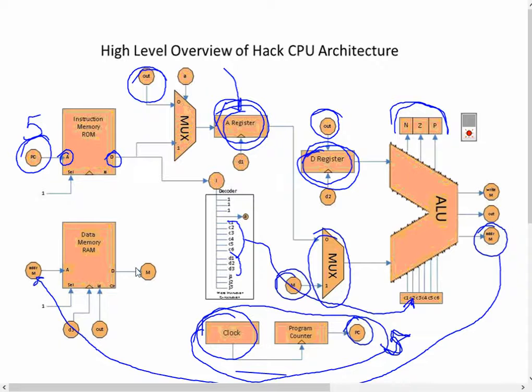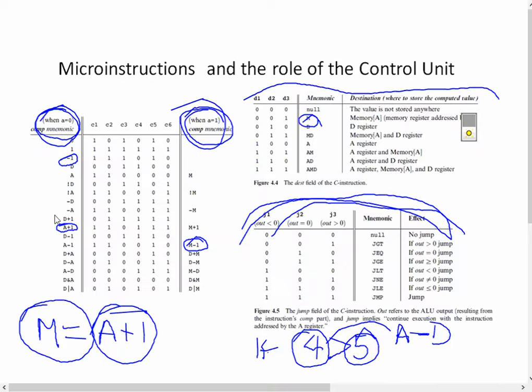You notice where it's sending is it's sending it out to the M, which basically is coming in here. And that represents the register for memory inbound. So again, we're down to those 3 registers. Memory register was bringing it out of the RAM and providing it into this MUX. I can have the A register, or I can have the D register. So you see all of the computations that we're performing are against A, D, or M. So you can see A here, D here, M here. Only A, D, and M are involved because I have to be able to perform computations using the registers.